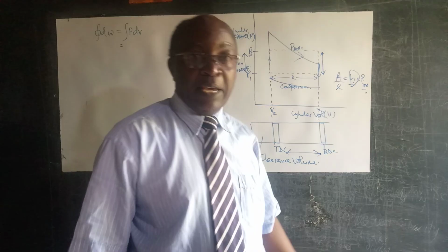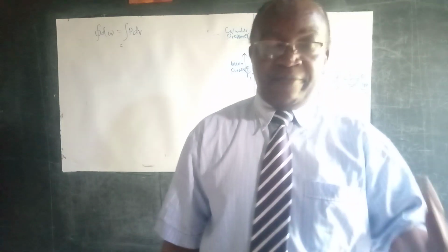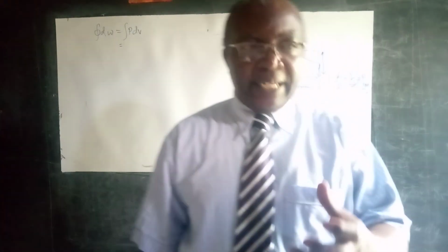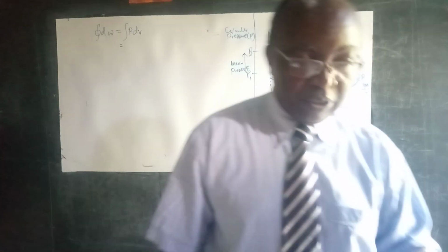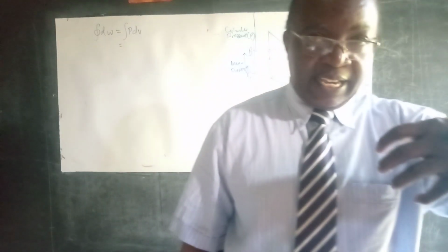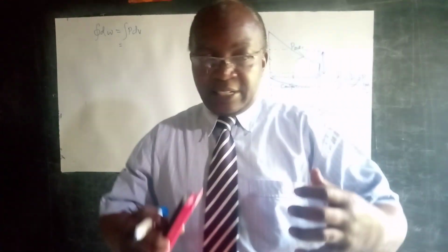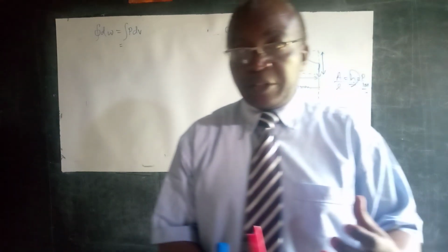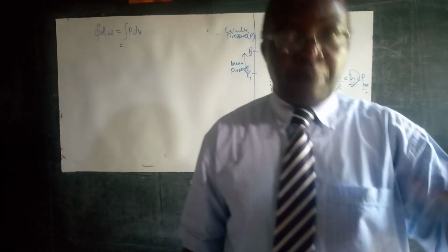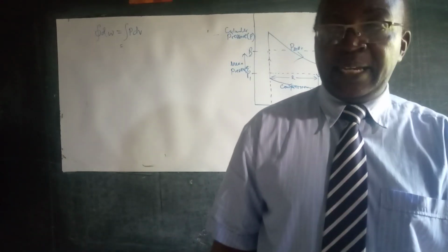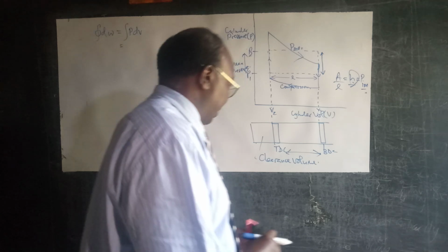That's the indicated mean pressure, the effective pressure. So what does that mean? That effective pressure, if it acts on that piston whose surface area is A, and it covers the engine piston stroke, then that will correspond basically to the work done by that particular machine.